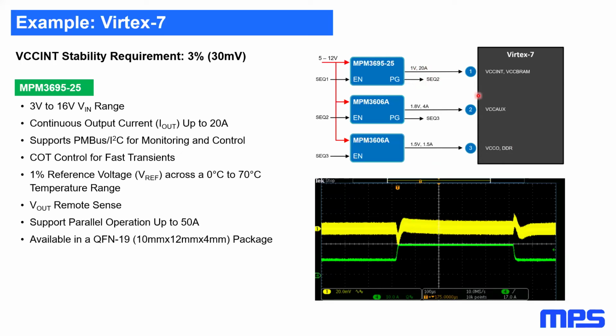And in this case, we can see very easily variations from, say, 2 or 3 amps up to 16, 17, very sharp, very high dV/dt, dI/dt in this load current change. And the requirement in the stabilities is often around 3%. So at 1 volt, this means that we can only vary about 30 millivolts when doing this load step.